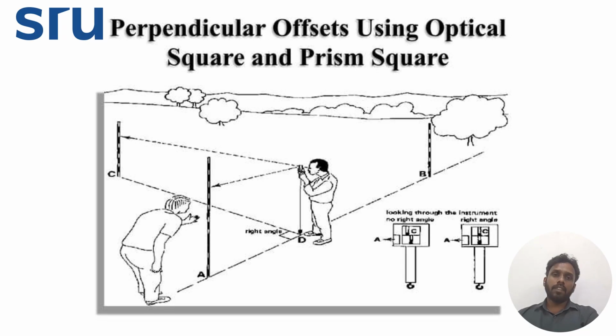So now they are verifying that point C and point D are exactly aligning. Once they fix this point C, again they are cross-checking point A, right? Because this is done by a surveyor, there may be a possibility of change in the inclination. So the right angle should be exactly measured, so it will be 90 degrees, to complete the entire procedure in an effective way. If there's deviation, you fix this, and if this is not aligning with A, then there's an error in fixing your offsets, which must be exactly perpendicular to your main survey line.